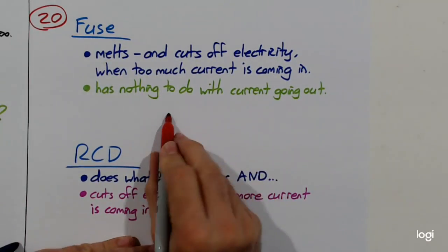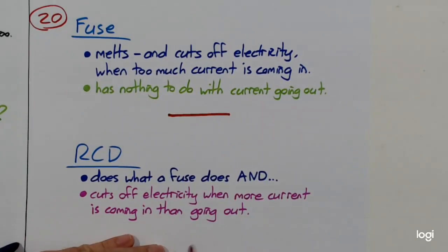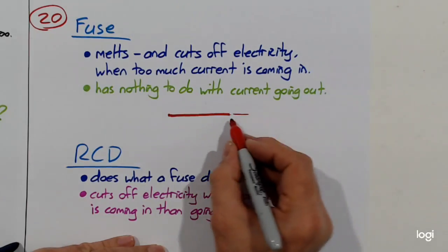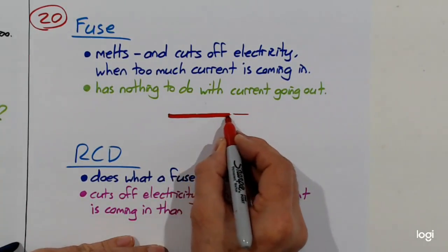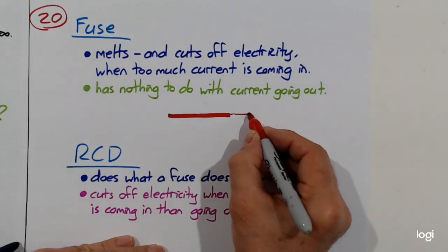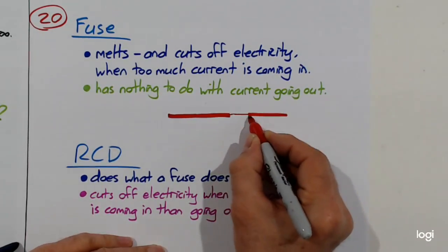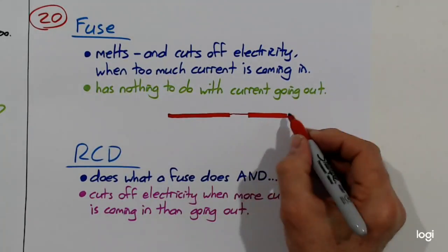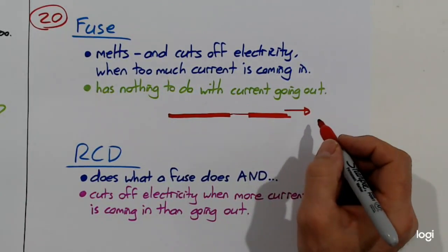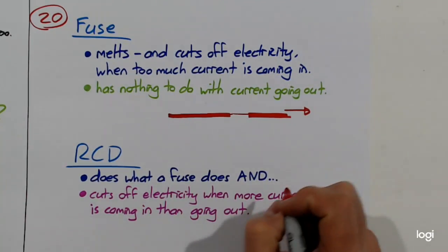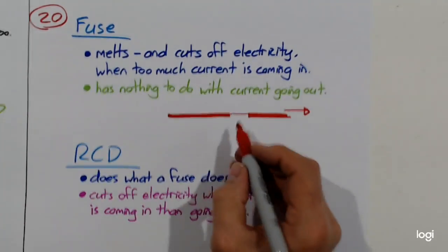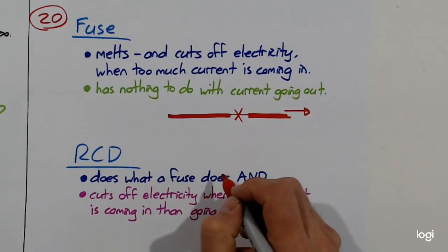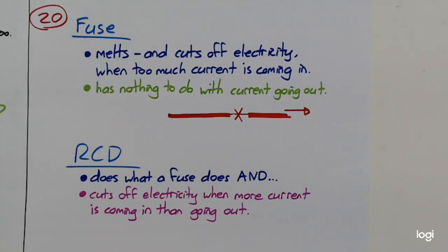If most of the wire that electricity goes through in your house is that fat, the fuse was very, very thin. And all of the electricity had to get through this tiny fuse at once to go into your home. If too much electricity was getting sucked into your home because you had too many things turned on, a toaster and the heater and the oven and someone turned the shower on, then so much current would be trying to get through that thin wire that it would break, it would melt. And that would stop all of the electricity from getting into the house.